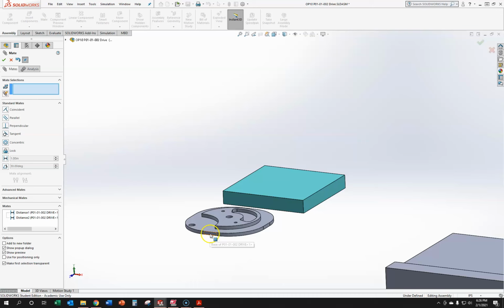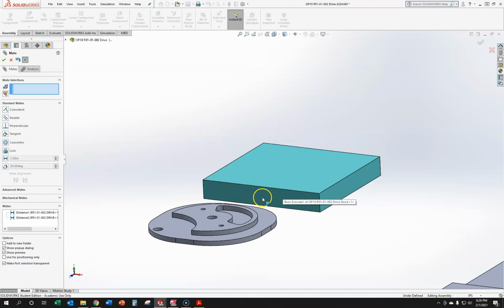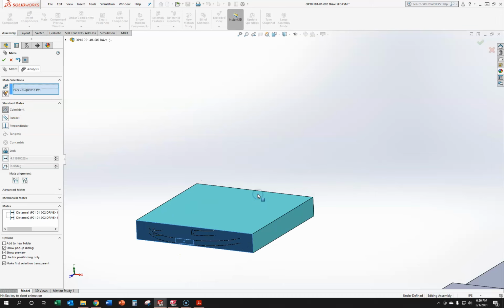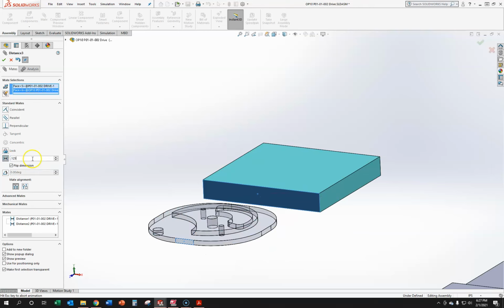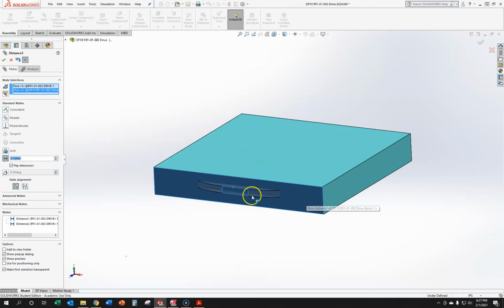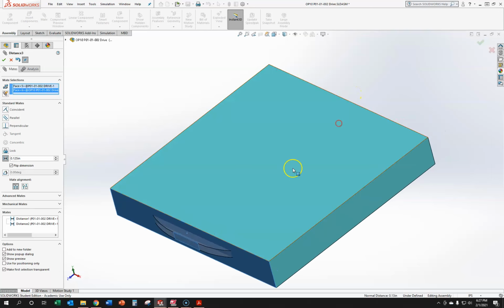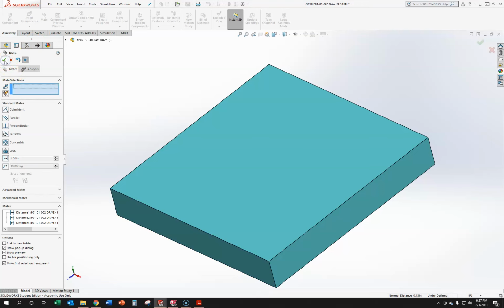Now I'm going to use this side here and do the same thing. We're going to have 1/8 inch offset. So I'm going to go ahead and mate this surface to that surface. And then I'm going to go ahead and do 0.125. If that's correct, the part should have disappeared. You'll notice that it didn't. So that means we need to flip that dimension. So if we uncheck the flip, it's going to go that direction on the inside. So now I'll click OK.